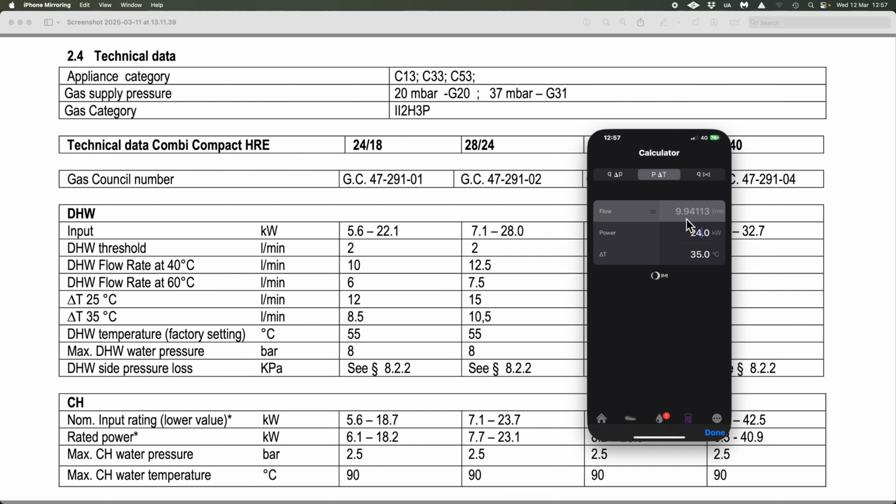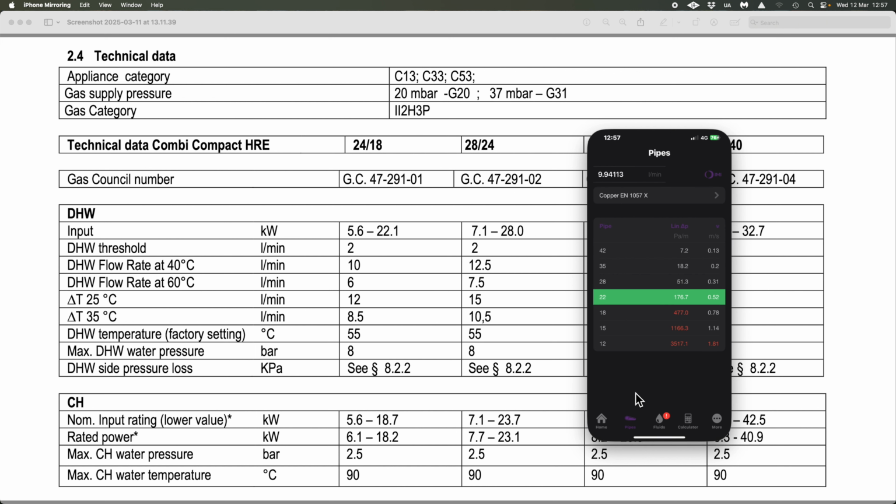And you can see we just get around 10 litres per minute there. 10 litres per minute. What's that going to do to our pipe sizing? Well, that's closer to our 15mm 1 metre per second Goldilocks zone, isn't it? And this is why I say that I don't think you need to be putting too many kilowatts down 15mm pipe on hot water heat up, because of the 3 points I made, which is system erosion, system corrosion, and component failure. 3 really important considerations when you're doing a design, in my opinion.